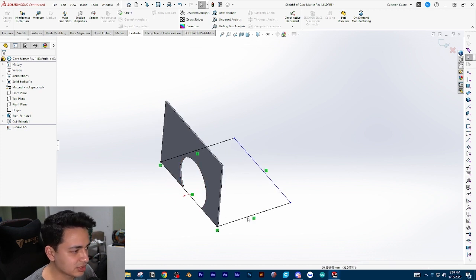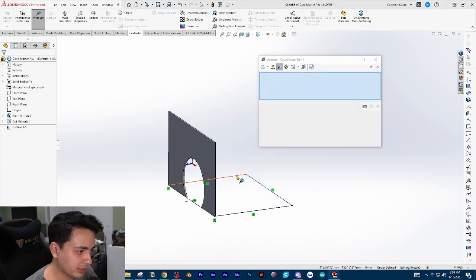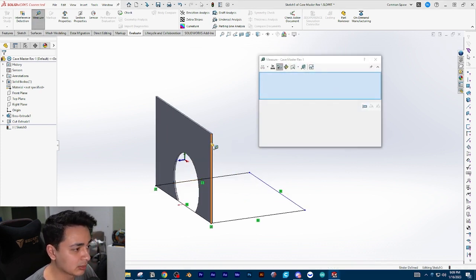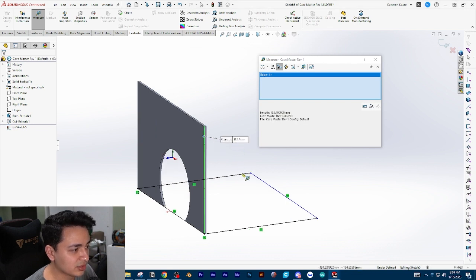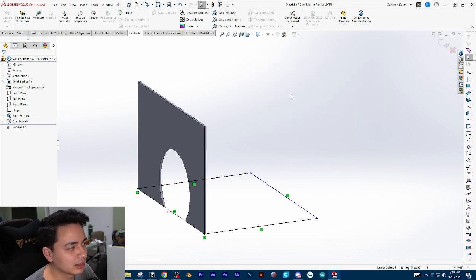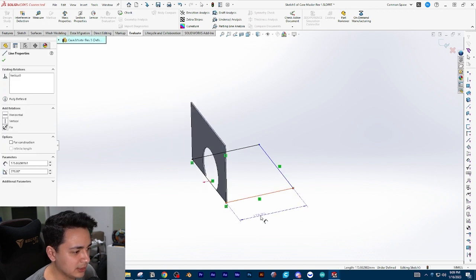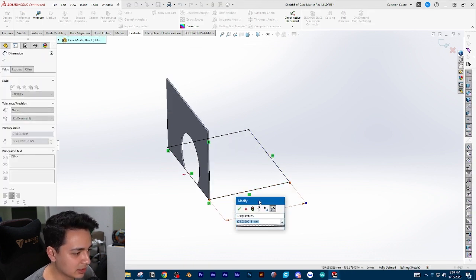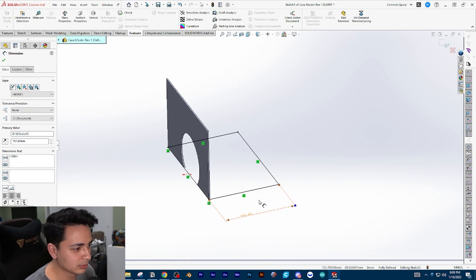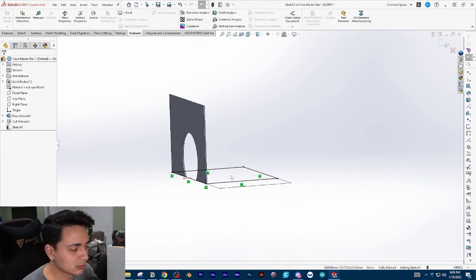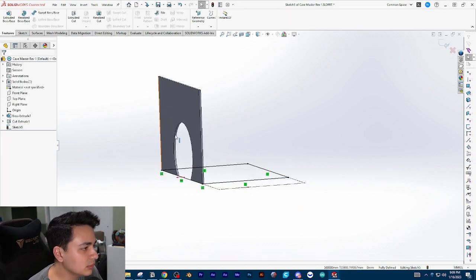so the lengths are the same of our pieces, right? So we need what is the height of our cardboard piece. So that's 152.4. A pretty useful thing is if you just left click this, it'll highlight and then it'll copy it. It'll store it on your clipboard. So now if I go to this guy and I dimension it and I just press Control V, boom, exactly how we want it. And then go back to features.